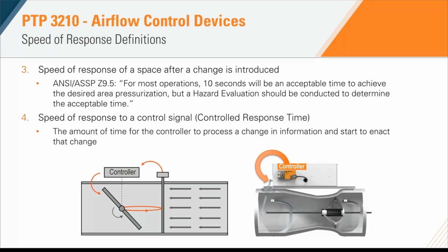But with Venturi valves, because there isn't a feedback loop where the air valve has to continuously sample the airstream and adjust accordingly, the Venturi valve will often operate very, very quickly out of the box with minimal parameters that need to be adjusted, since the duct pressure fluctuations won't affect how the actual valve controls to the airflow set point changes.